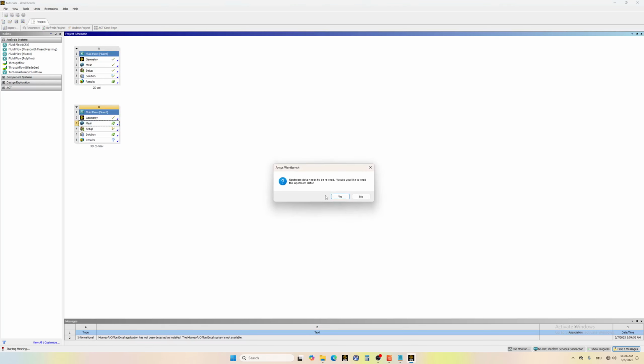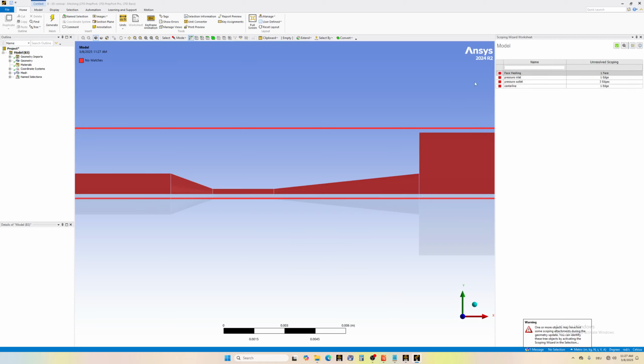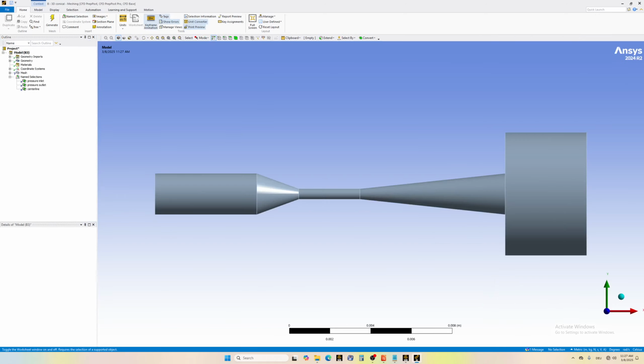Okay, let's open the mesh program. Now we wait to update the geometry. Alrighty. So here it complains about the name of the boundaries because it's a different geometry, so it doesn't recognize them. You see here an XXX, that means you have to redefine them, which we are going to do now. It's easier.